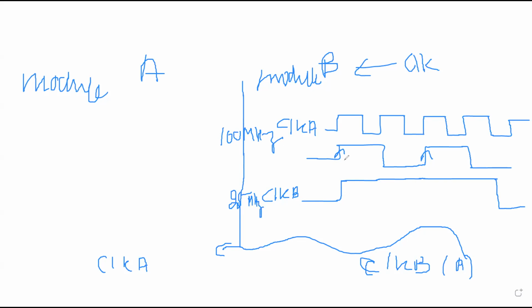Yes. So let's suppose there is signal A, which is in clock domain A, and that signal is moving from clock domain A to clock domain B. If we just sample that data at this edge, it would be 1, and this will go, this will go, and we would say that it is continuously 1 in domain B. But if we look inside the signal, there is a toggling from 1 to 0 and then 0 to 1, correct?